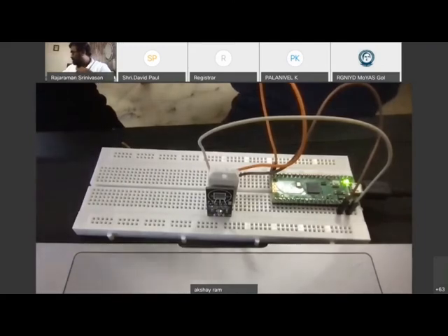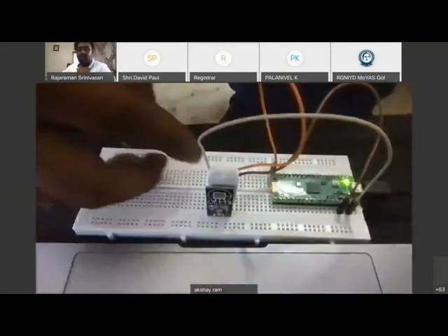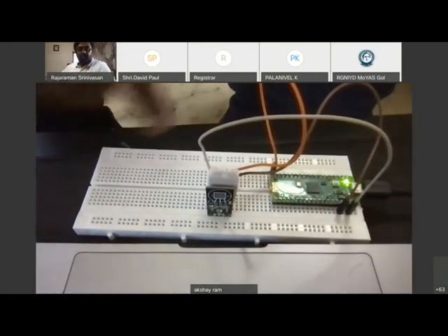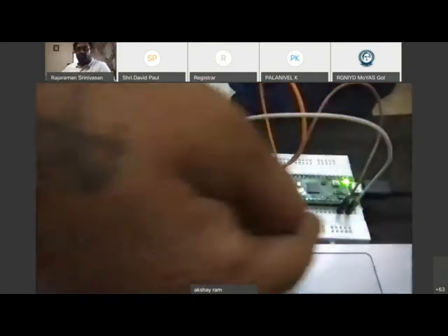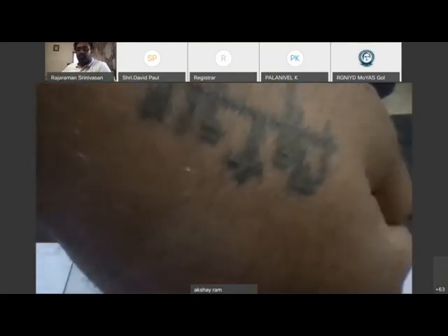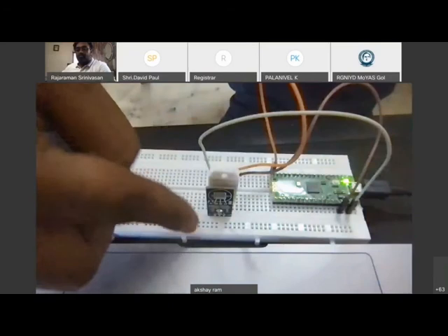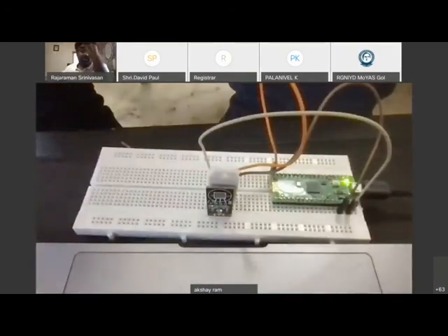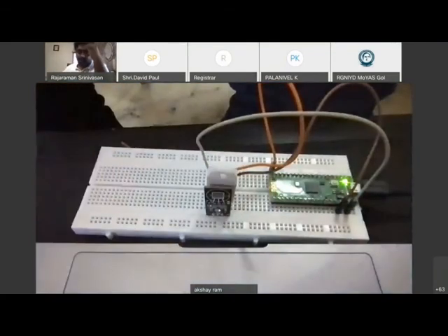So instead of using each one of them to ground here, we would connect them to the rails. If I am using the rails, I'll be using another extra set of jumper wires that go from here to here, and then from here to here. So now we are just directly connected. It doesn't actually make a difference. If we want, we can power it from the rails also.